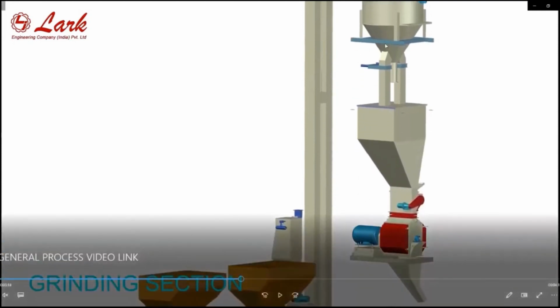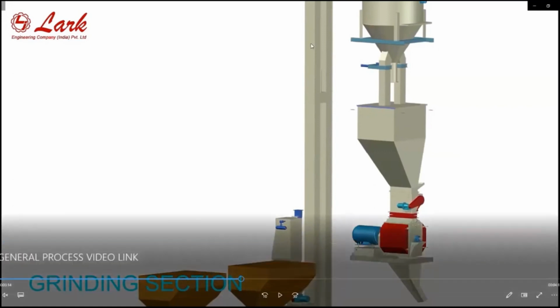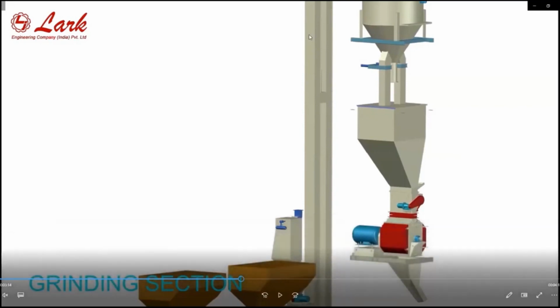After the pre-mixing, there is a buffer hopper of the hammer mill, and then there is a rotary vane feeder with a VFD. This rotary vane feeder motor is synchronized with the main motor of the hammer mill with the help of the VFD. The hammer mill is around 75 HP in a 5-ton feed mill, or 150 HP in a 10-ton feed mill, and the ideal current of a 150 HP hammer mill is around 180 amperes, as the motor is of 2800 RPM.